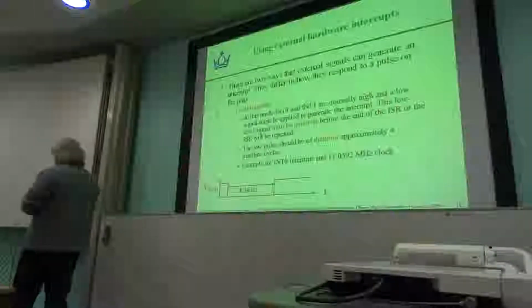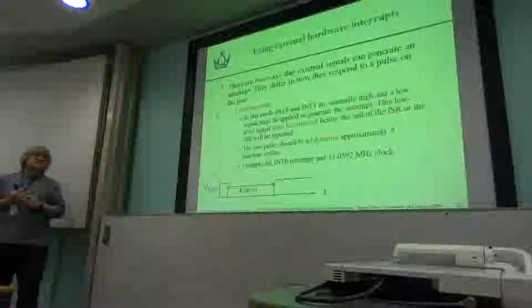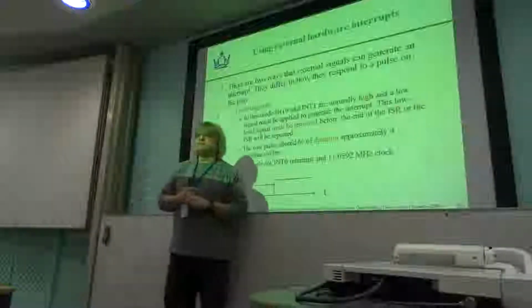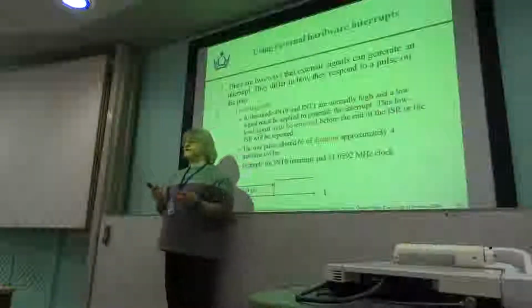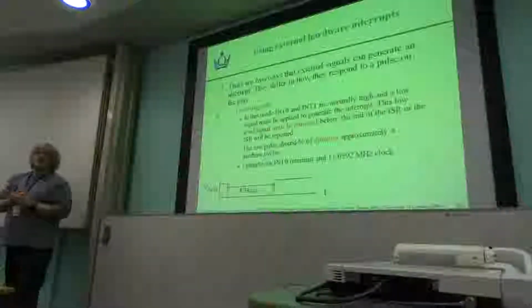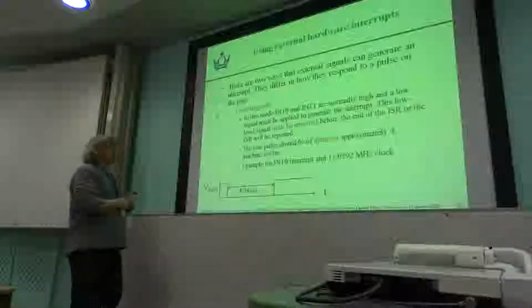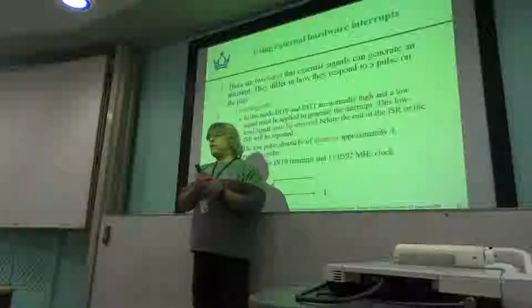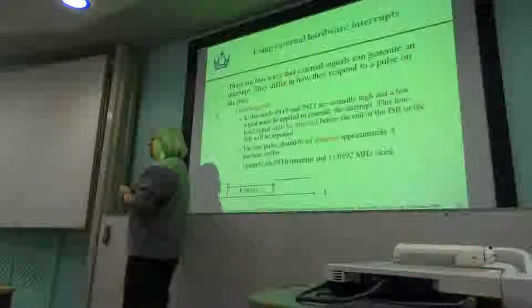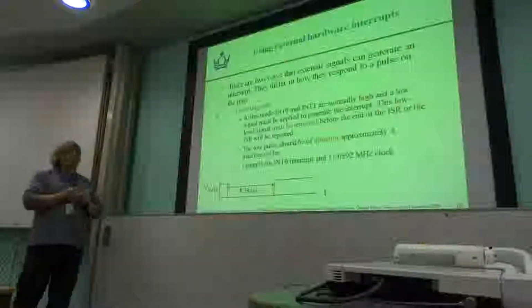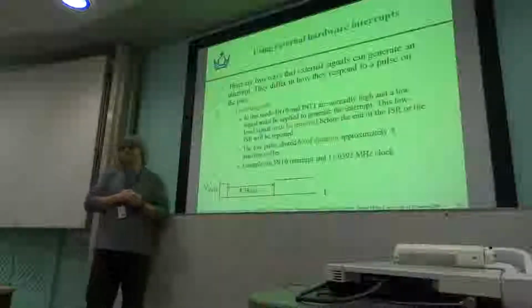So we've talked about the timers. You now know 2 ways of playing around with timers. Well, you know lots and lots of things about timers. You've used timers as counters, timers as timers. You know about all the different modes of timers. And we've got 2 ways of monitoring when the overflow takes place. We can poll the TF flag, or we can use interrupts so that when the TF flag gets set, automatically we're taken to an interrupt service routine.